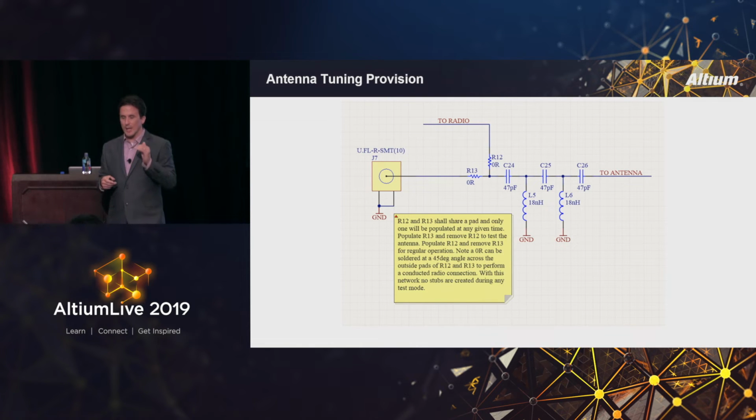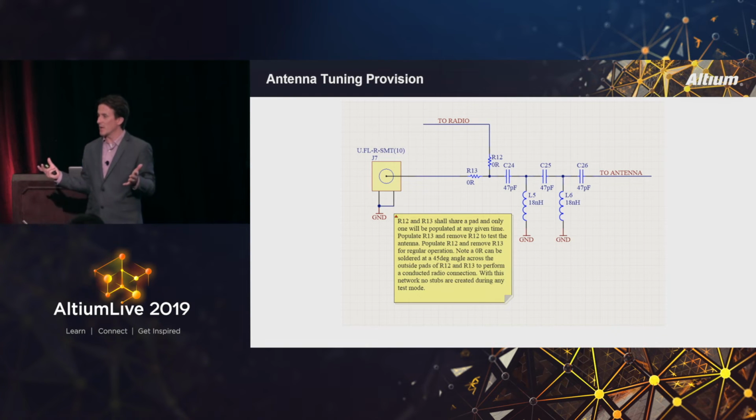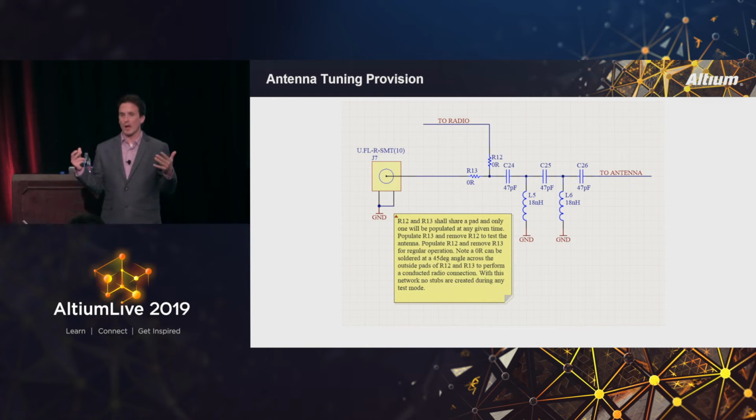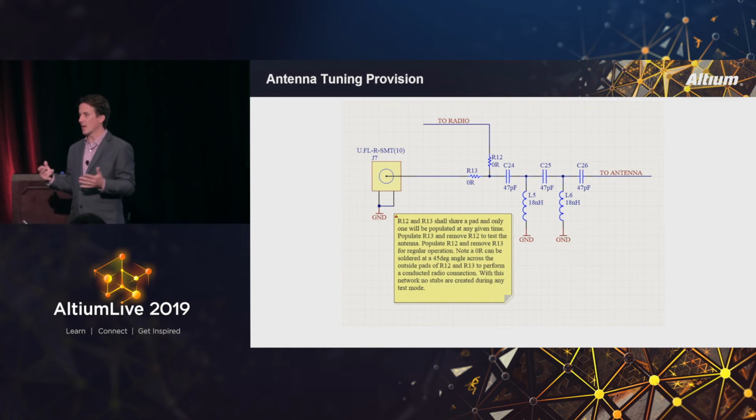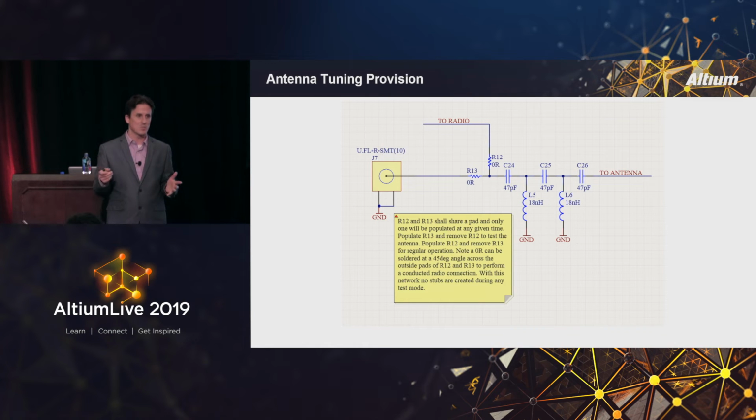And I want to emphasize this again, this was a learning for me: even RF transparent materials, so plastics, change the characteristics of your antenna, not by a ton, but they change, and your antenna needs to be tuned after it's put into the case.